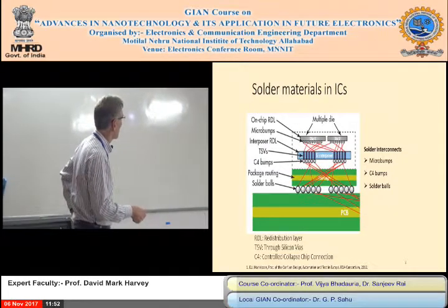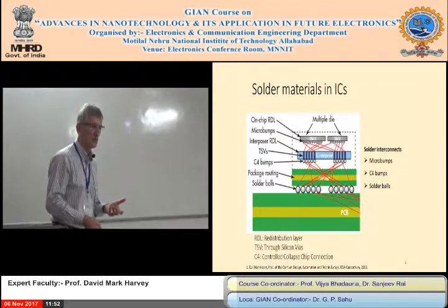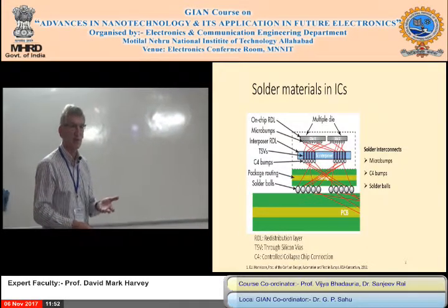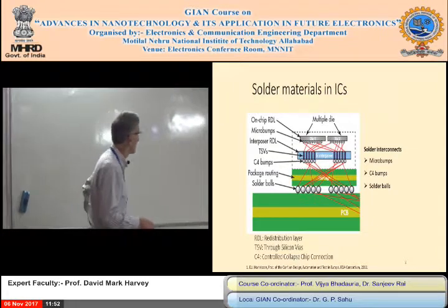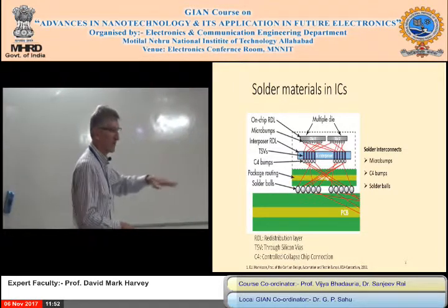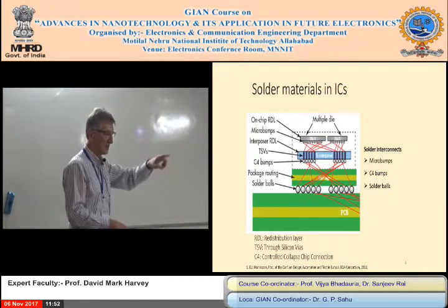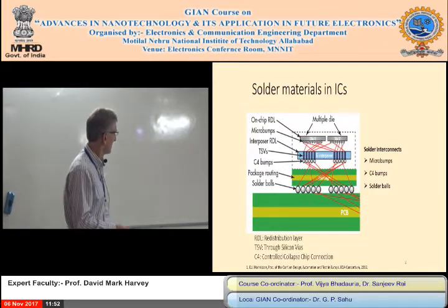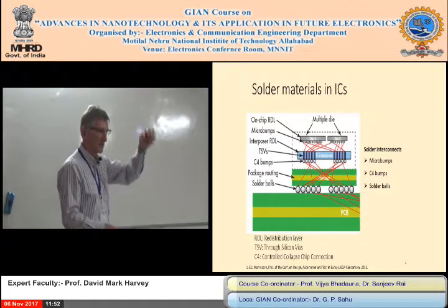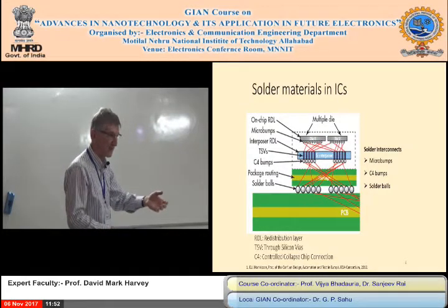And in this one, you've got what we call different things, multi-chip module, stuff like this, more than one chip in a module. So here you've got multiple die on the top, with only 2 shown, but you could have more than 2. Then they're all connected through. These are the latest things for connection. We used to use bond wires, now we use what we call TSVs, which are through silicon vias. So silicon to silicon connections, and you get problems with these as well.